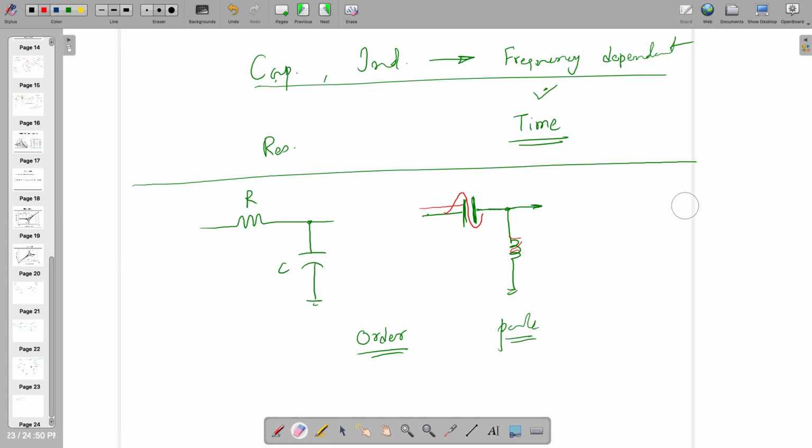So what kind of filter is it? Okay, high pass filter, right? Everybody agrees, high pass. And the system will always be unstable, by the way, because it's going to contribute minus 40 dB per decade, and the phase margin will be exactly 0 degrees, because two poles are at the same location.